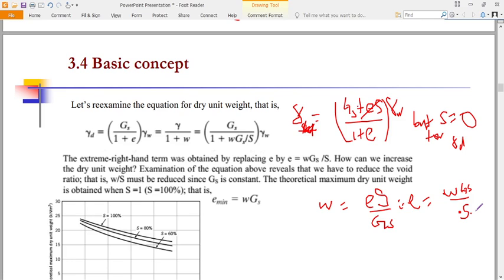These are linear plots, relating moisture content and compaction. What is the importance of moisture content? The degree of compaction of soil is measured by the unit weight and optimum moisture content. Remember, you want to get the water at which the material can give the maximum strength, when you have lubricated all the soil particles such that the material is compacted into a dense mass. By reducing the air voids, moisture can be added to the block. When moisture is added to the block, the water content w is increasing, and the soil particles will slip on each other.